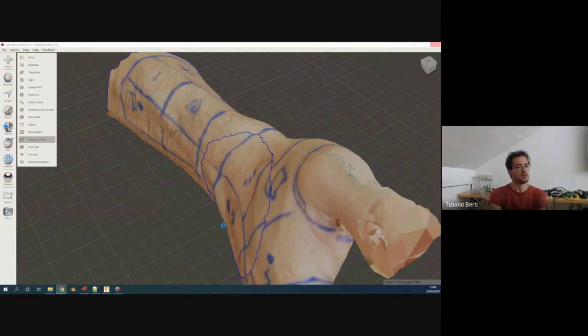In order to keep everything pretty fast, you need to in some way clean the RAM while working. So the best way is to remove all the objects that are too heavy to work with. If you're working with a full scan of a body, it's better first to select the part you are working on, decimate, reduce the resolution, and export the high resolution mesh.